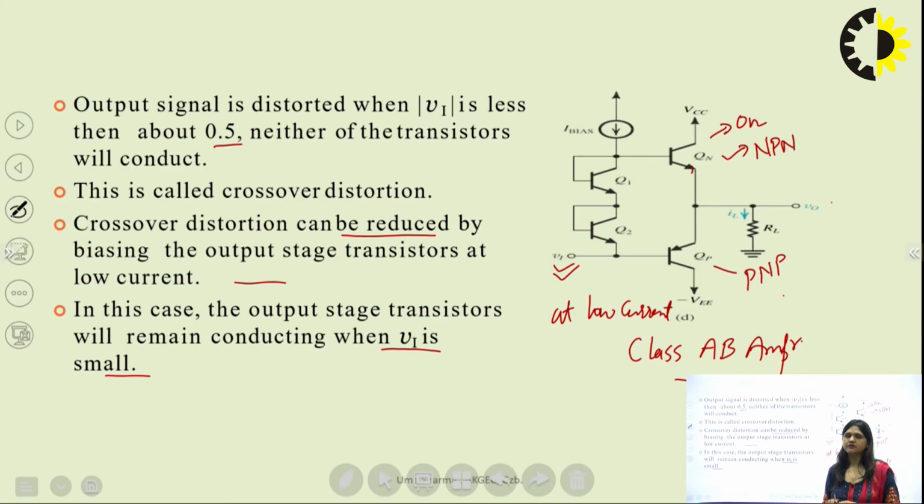So overall this 741 IC is divided into 5 subsections, and we have noticed one thing. There is one capacitor which is connected at the output stage, and this capacitor is responsible for the frequency compensation. With the help of this capacitor, we can nullify the effect of parasitic capacitances. Once we have studied the different stages, we have to analyze these stages for DC configuration as well as for the small signal. We have to do the analysis in the DC domain as well as the AC domain.